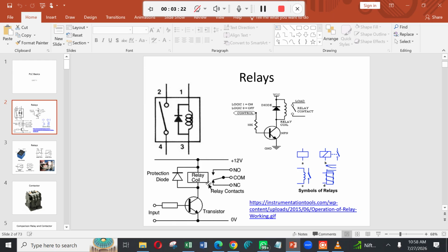Fine, like that. So in this circuit, along with the relay coil, there is a contacts. You can see this contact. I mentioned NC, NO, common. Already we discussed what is normally closed, normally open, like these things. So the same thing has been used here. So what's happening here? When there is no power supply, the common contact, this moving contact, will stay with the NC.